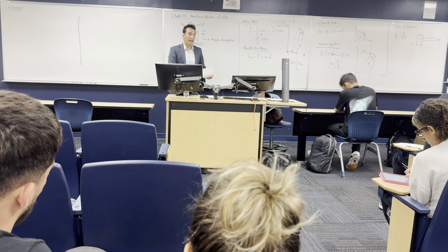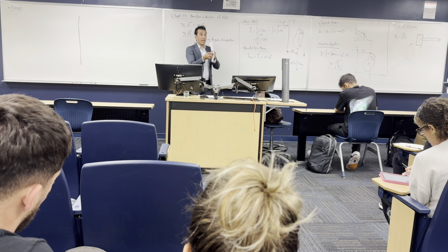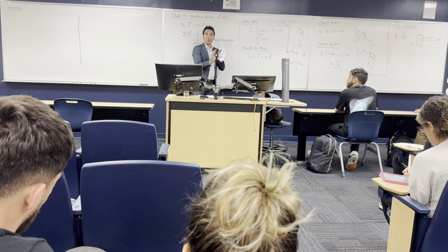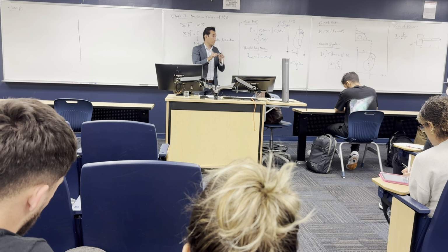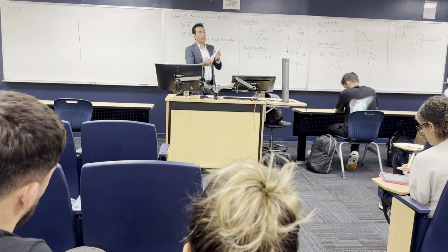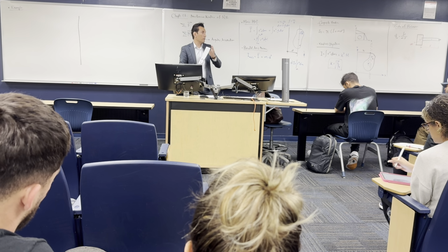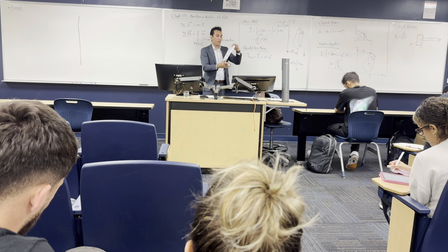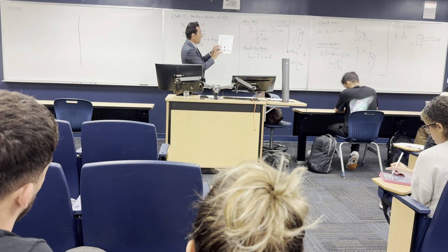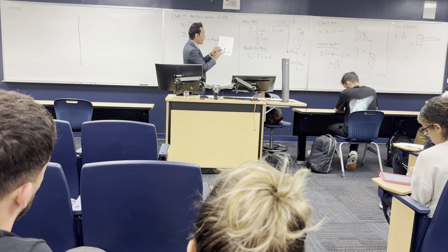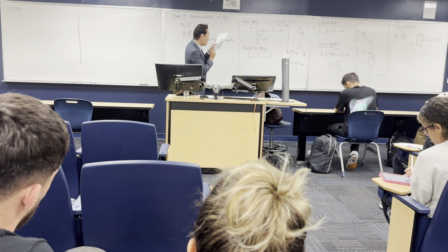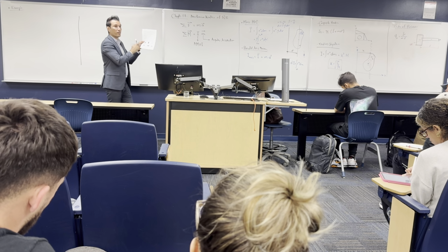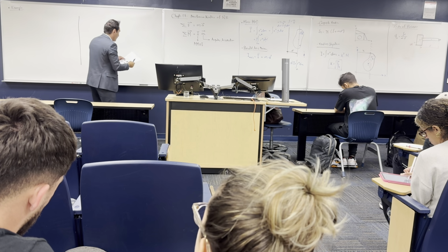How about rectangles? Rectangles, I about x is the same as I about y because it's the same dimension in x and y, okay? But z is going to be different. Sorry, I meant square. Okay, not rectangle. For a rectangle, x and y are different, so it's going to be different. So here I'm giving you everything: Ixx, Iyy, Izz, and for the cylinder, I have the final answer, but let's prove the cylinder and look at the sheets and see if we get it right or not.